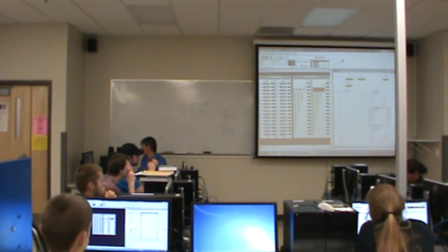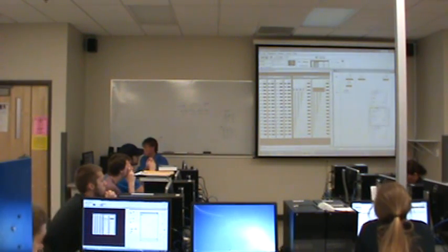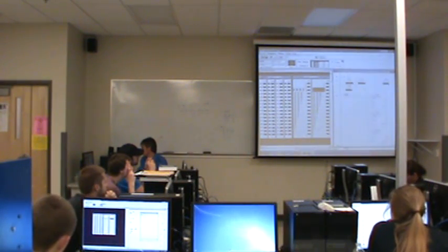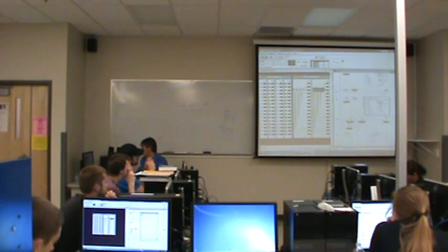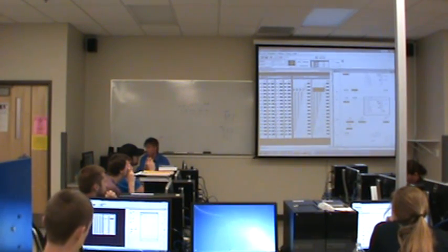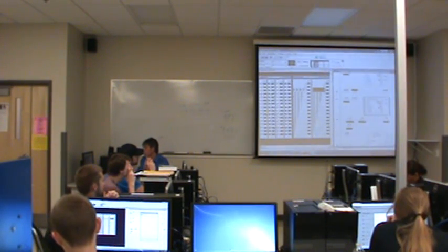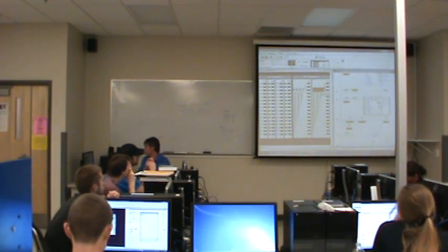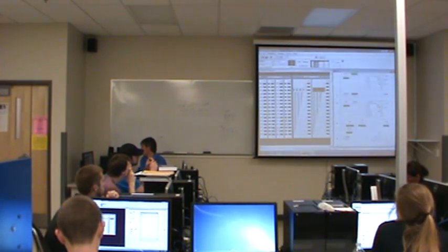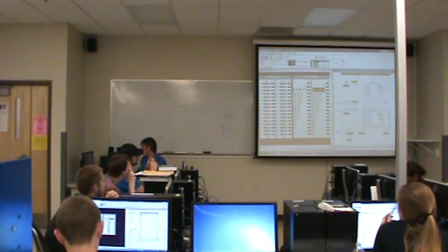Basically, it will ignore, now be careful, this is not the inputs, these are the outputs. Because B311 through B318 are associated with the output instruction. So what I'm doing is I'm masking off all of these other outputs except for the low nibble. And you remember that the only number that changed was this low number. Now we can explore the masks for the sequence compare and sequence output.